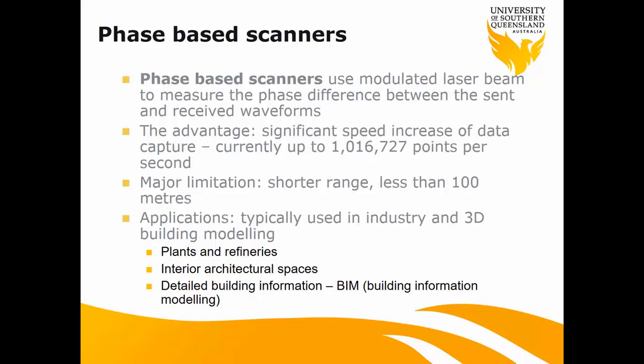The next one is the phase-based laser scanner. The advantage of this is high-speed scanning, so in a very short time we can get more point data. For example, phase-based laser scanners can collect up to 1 million points per second.